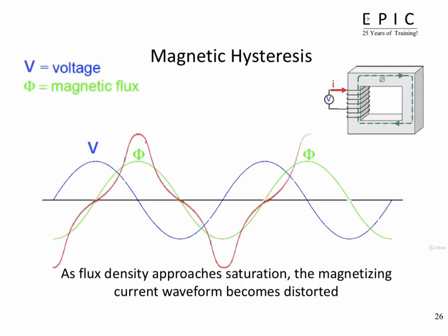When a ferromagnetic material approaches magnetic flux saturation, disproportionate levels of magnetic field force, MMF, are required to deliver equal increases in the magnetic field flux, phi. As you can see from the graph, a large increase of MMF is required to supply the needed increases in flux, which results in a large increase in coil current.